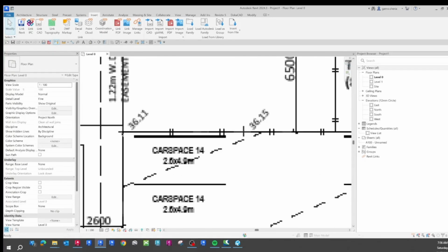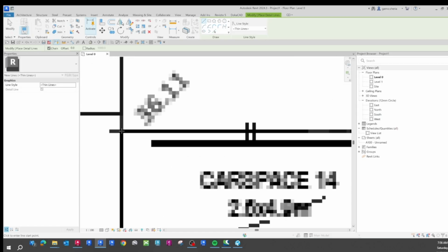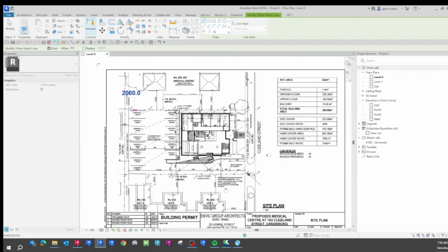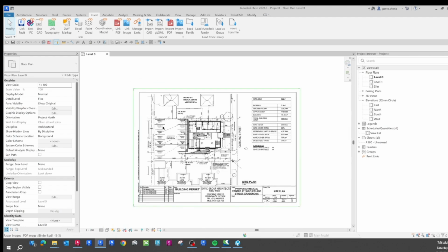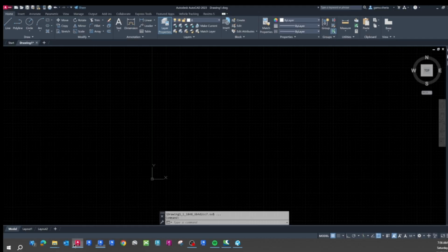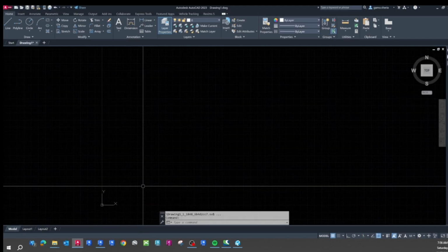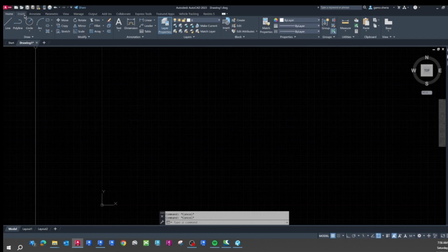But like I said before, if I try to draw lines, I'm going to have to eye it to the center, which means my setout is not going to be very accurate. For that, I then use AutoCAD. So I'll delete that, go to AutoCAD. AutoCAD has the ability to convert a PDF to lines, and you do the same process.